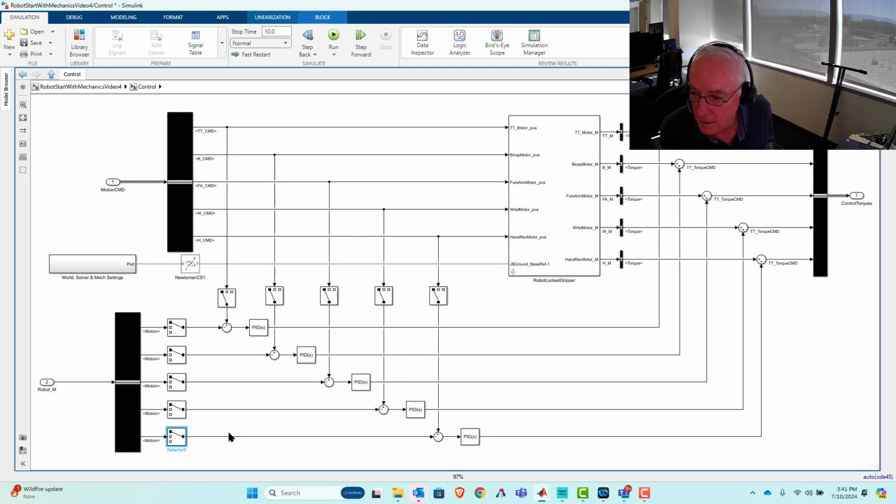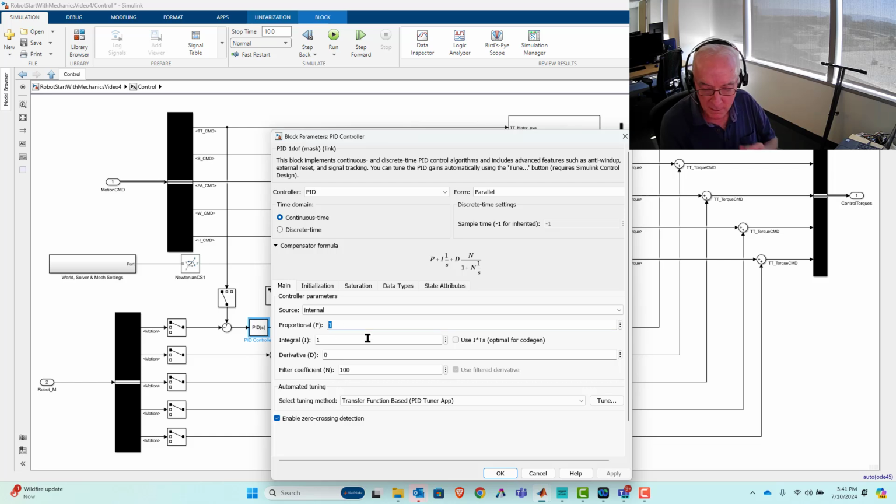Okay, so I think I got that. All right, so a little bit of cleanup, a couple of things actually. I think I'll do it here first. All right, default values on the PID controllers we pulled out of Simulink is 1, 1. So KP is 1. The proportional gain, that's what KP is. The integral gain is 1, and the derivative gain is 0. All right. Perhaps I'll do a video where I get a little bit more into where PID comes from. They probably do have a few videos out there on it, and certainly MathWorks does too. But anyways, I won't elaborate on that now.